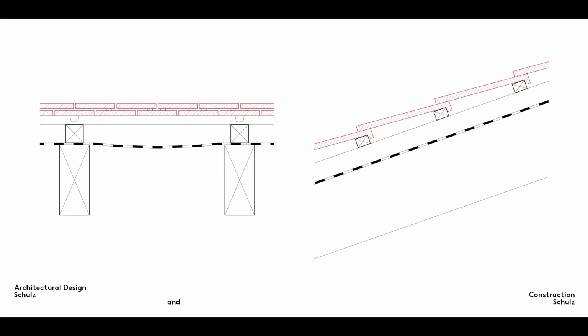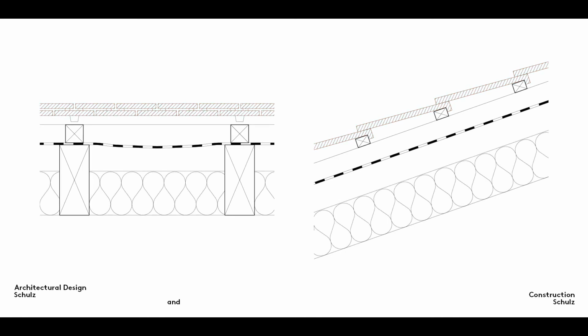Finally, the roof tiles are laid on the battens. Because the tiles have to overlap, they are always laid from eaves to ridge. In the example shown here, the lip at the back of each tile is hooked over the rear edge of the battens. The rest of the roofing work takes place inside the roof space. The insulation, generally soft mineral fiber insulation, is then fitted between the rafters. The rafters are deeper than the thickness of the insulation. This helps to ventilate the space between the insulation and the sarking membrane and to dissipate heat and water vapor.